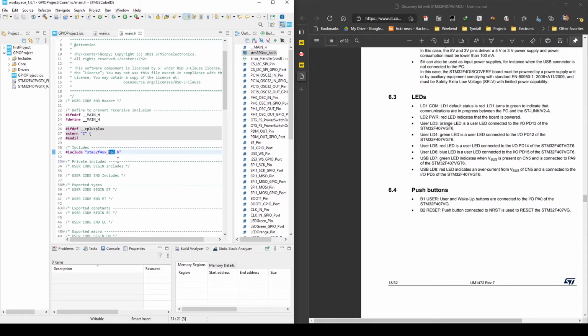In microcontrollers, you are basically working with registers and a lot of 0 and 1s in some registers. So working with those registers is not always as easy as it seems. So this HAL library will provide you some, let's say, closer to human level functions, so that you don't need to be worried about those 0 and 1s in the microcontroller configuration.